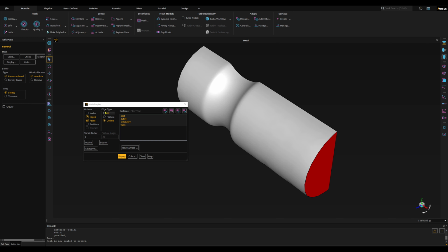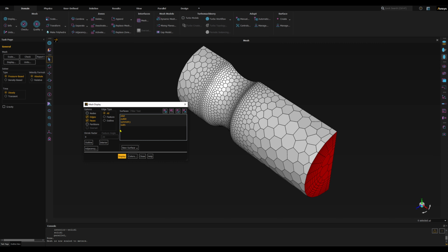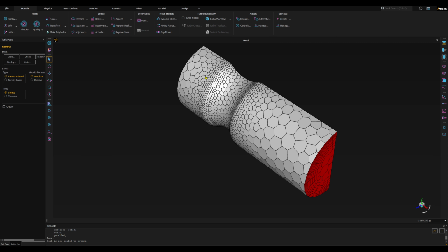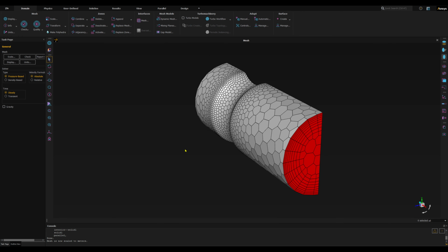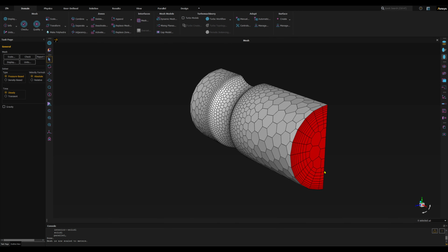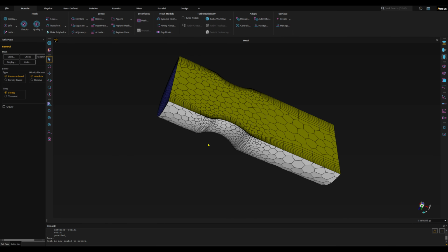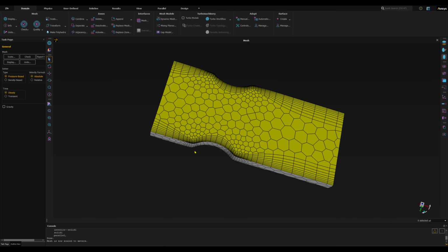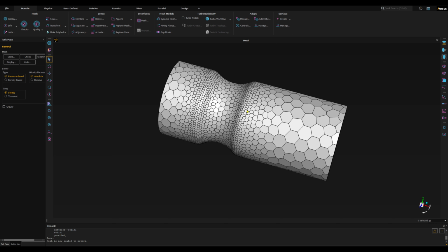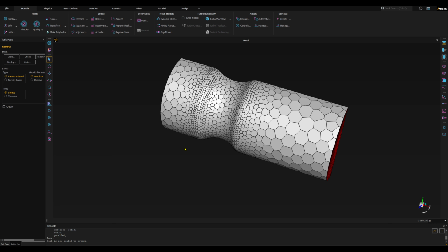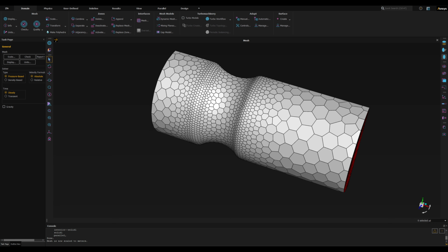You can also set the edge type to all to see the mesh. So I will select this one and use display and then close. You can see the mesh, the boundary layers around the walls on both sides. And also here, as you can see, this is our mesh. It's a coarse mesh actually, but we will use mesh refinement for our problem.